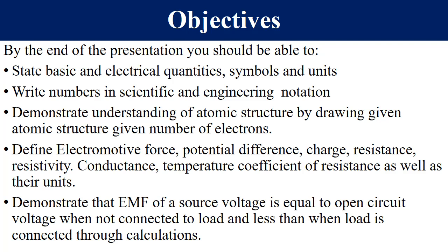You must also be able to demonstrate this important fact that the EMF, electromotive force of a source, is equal to the open circuit voltage when no load is connected. But when a load is connected to a source voltage, then the terminal voltage becomes less than the source voltage or the EMF because of the drop across the internal resistor.